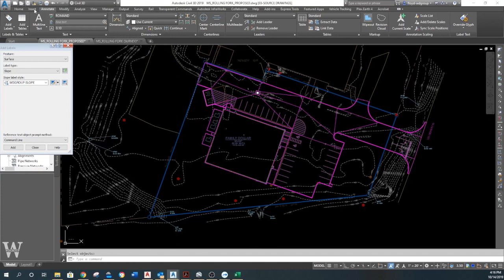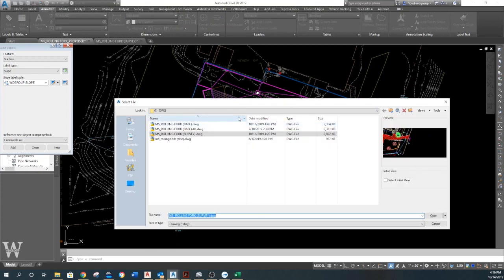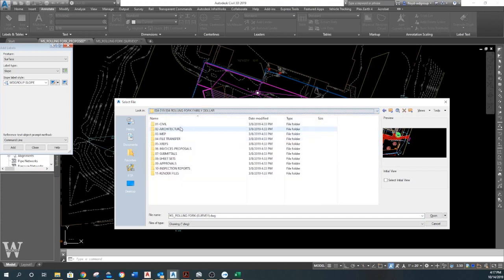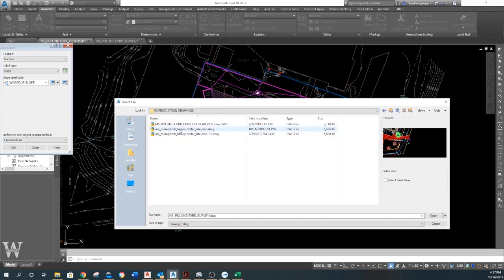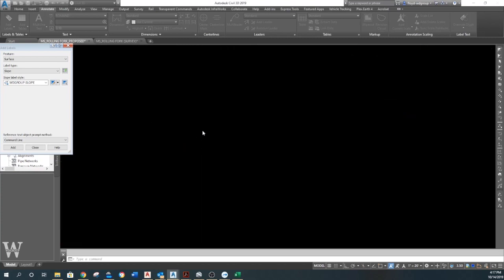Okay. Now I'm going to go back to my design drawing. Because now I've got to determine what my post-condition flow rates are. Well, the first thing I got to do is divide the site into two pieces. Because I got a front and a back, and basically the only thing that goes to the back is that inlet, where I put that inlet in, and then the building. Everything else is going to the front, okay?